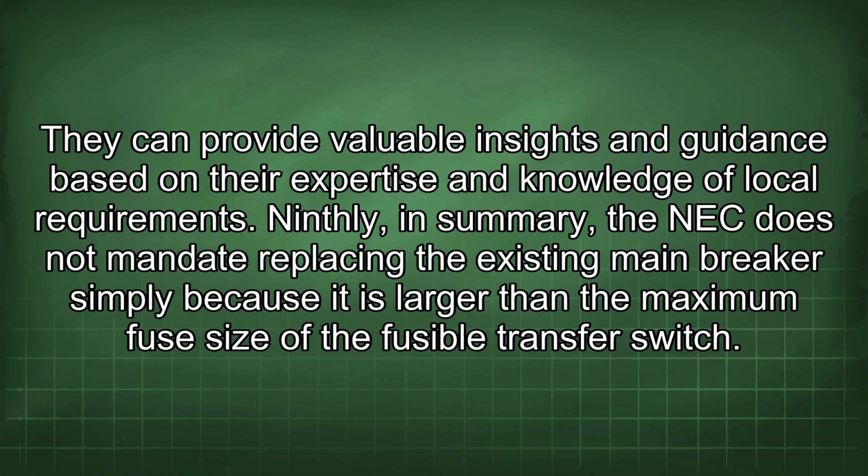Ninthly, in summary, the NEC does not mandate replacing the existing main breaker simply because it is larger than the maximum fuse size of the fusible transfer switch.